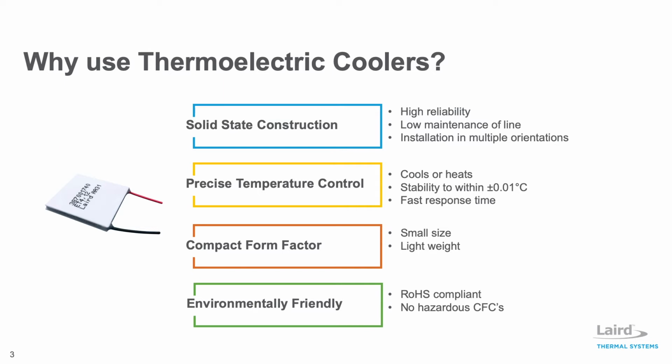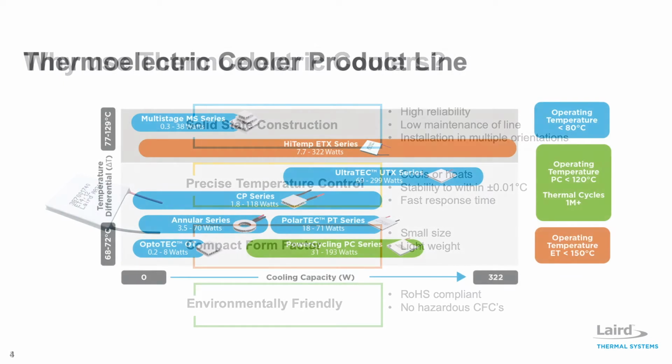This allows temperature control to be very precise, where up to 0.01 degrees Celsius can be maintained under steady-state conditions. Their lightweight and compact form factor make them ideal for applications where size is limited. In addition, thermoelectrics have minimal electrical noise and are environmentally friendly because they use no CFCs.